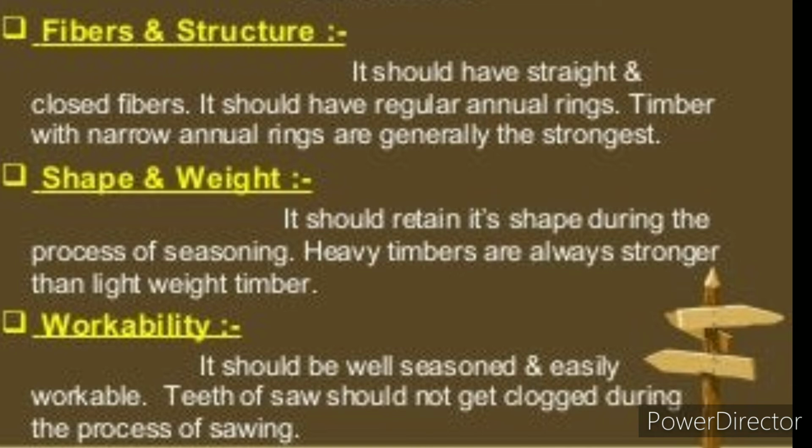7. Odor. A good timber should have a sweet smell. An unpleasant smell indicates that the timber is decayed. 8. Strength and toughness. A good timber should be strong and tough. That is, it should be capable of taking loads slowly or suddenly. It should also be capable of offering resistance to shocks due to vibrations.